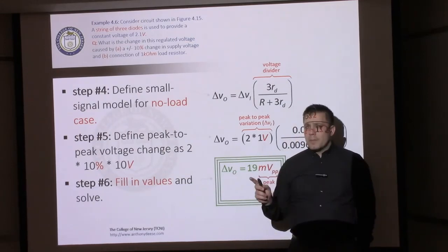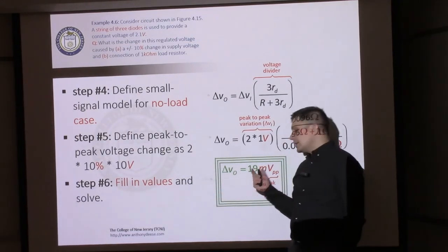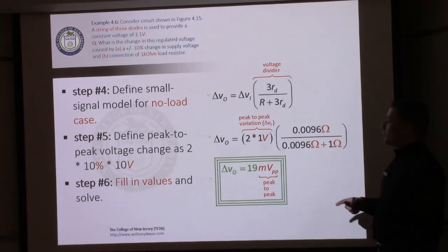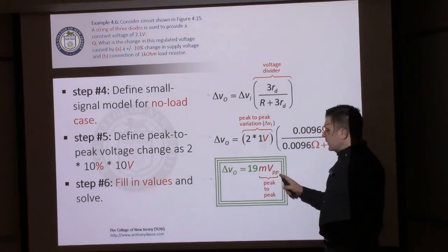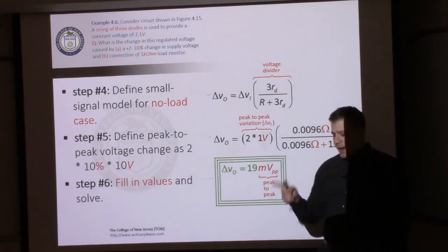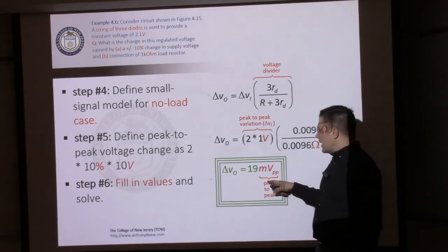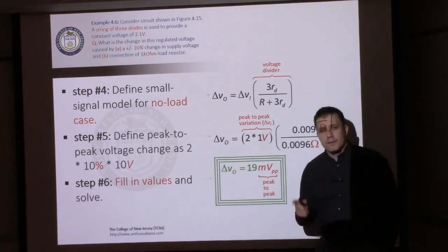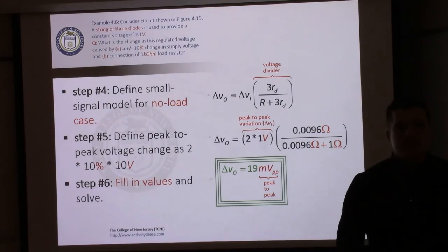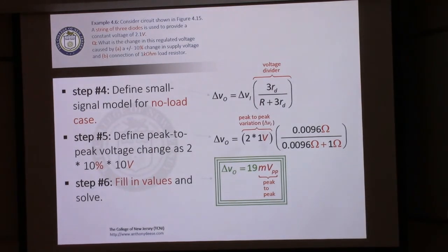The answer, although it may seem like no, is actually yes. And there's a little bit of a conversion that we have to use. First off, the 5 millivolts is not compared to the peak to peak value, it's compared to the amplitude. So we need to start off by dividing this by 2. That brings us down from 19 to 9.5. That's still above the 5 millivolt limit.